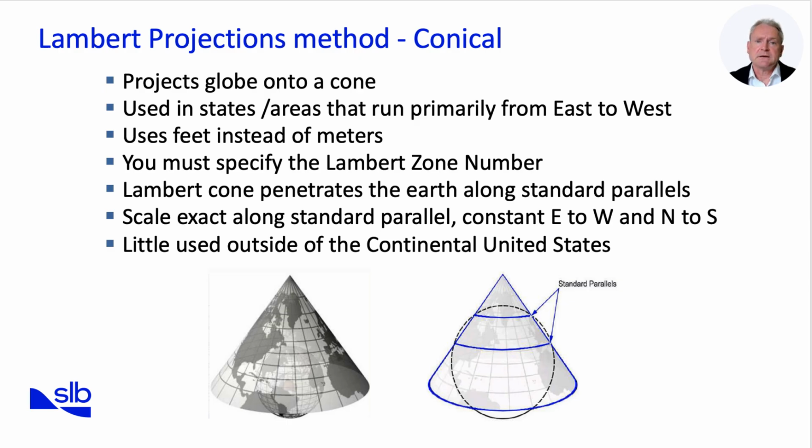One key detail is that Lambert projections often use feet rather than meters, which requires vigilance when converting data into international oil field systems that typically use metric units. Another important note, users must specify the correct Lambert zone number, since scale and alignment depend on the standard parallels used. Although not widely used outside North America, it remains important when collaborating with US-based datasets or legacy maps.